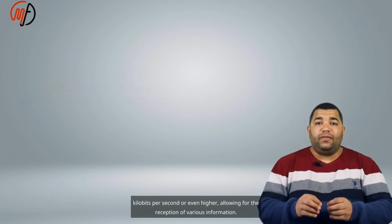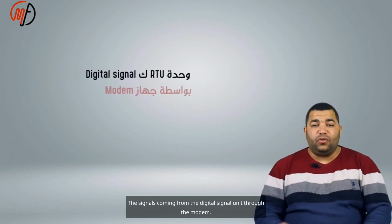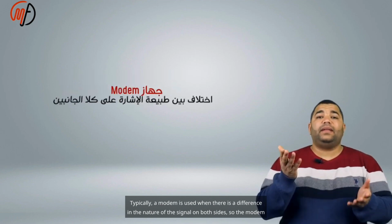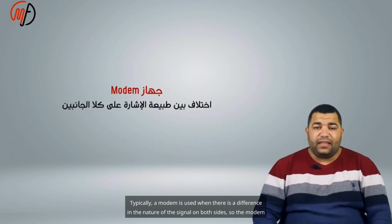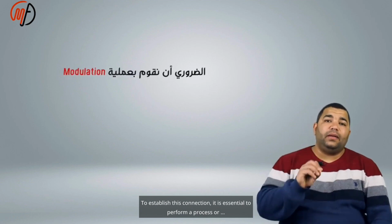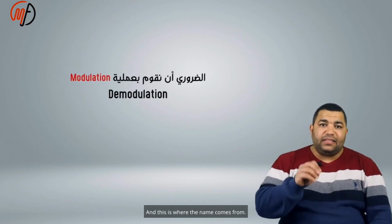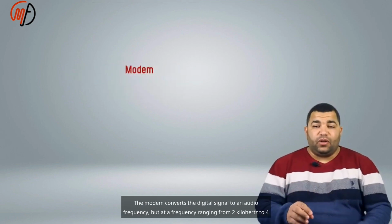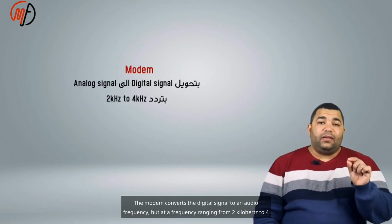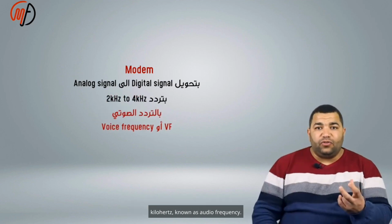This allows for the reception of various information. The signals come from the digital signal unit through the modem. Typically, a modem is used when there is a difference in the nature of the signal on both sides, so the modem connects them. To establish this connection, it is essential to perform a process, and this is where the name comes from. The modem converts the digital signal to an audio frequency, ranging from 2 kilohertz to 4 kilohertz, known as audio frequency.